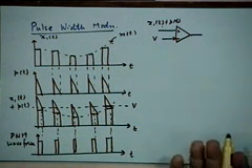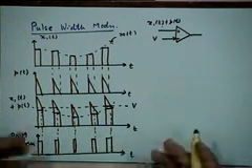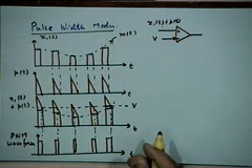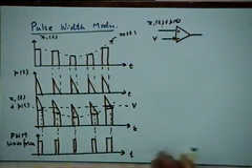So, that is really as simple as that. This is one way of generating the PWM waveform. There are others, but this is one way. So now my information about m(t) is in the width of the pulse, and that is what you will transmit.